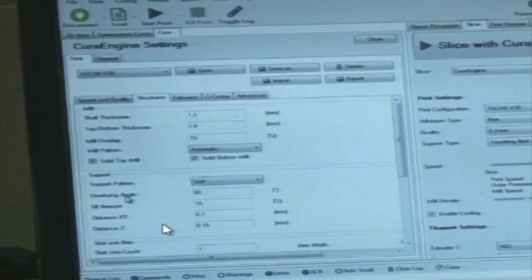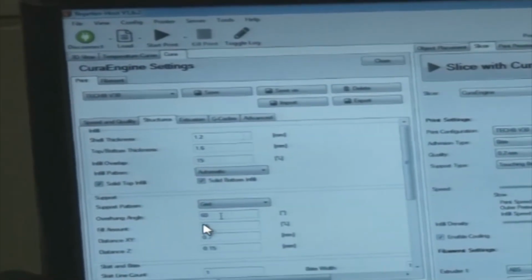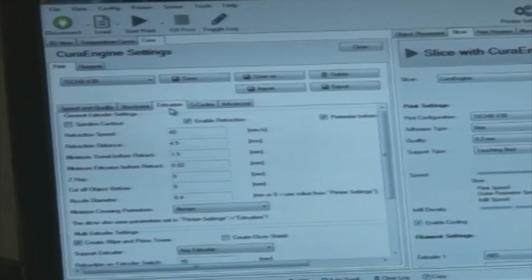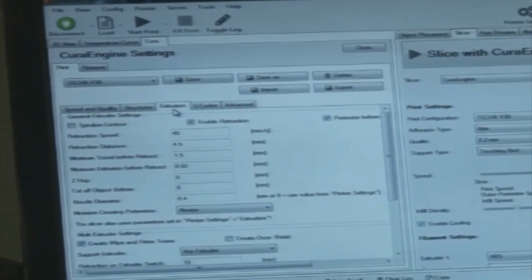And next what we have here, we need to see whether there is anything overhanging in the CAD model. In the CAD model, if anything overhanging is there, then we need to put this angle. If anything is overhung, then we need to provide this support, and only then we can proceed further. So then the overhang angle has to be decided.